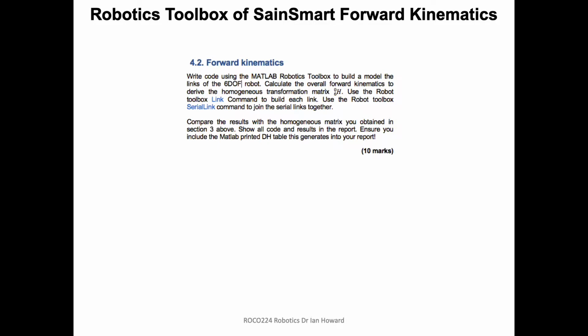link homogeneous transformations. And this is a really good way of checking that your Denavit-Hartenberg coordinate system is correct, and it actually gives you the same results as you got when you did the analysis by hand. So I'd very much suggest you do check every single link homogeneous transformation and make sure it agrees completely with what you had before. I also strongly suggest you not to evaluate it at any particular value of theta, which is the control variable. Leave theta as a symbolic variable, and then you've got the proper equation for each of